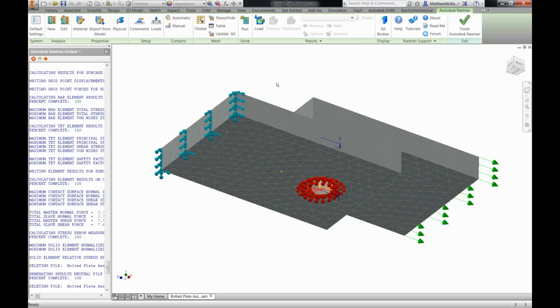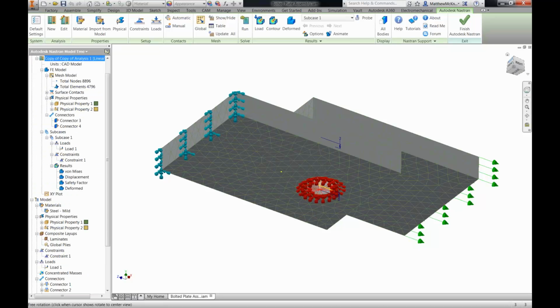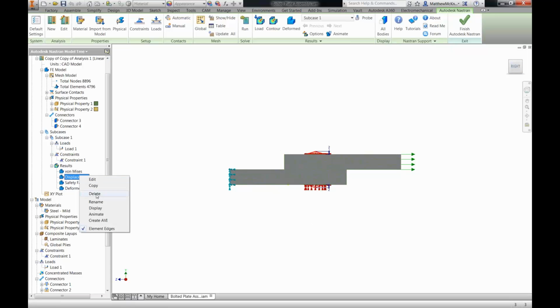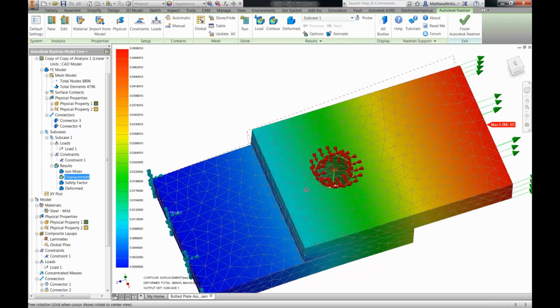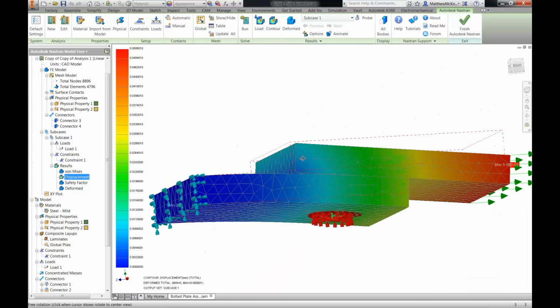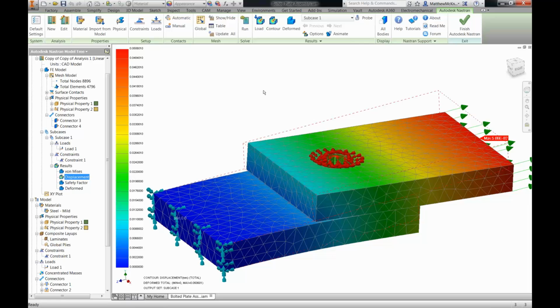And it's just finishing up now. So let's have a look and turn on our displacement plot display. And you'll see here, like we've seen before, very similar result. We're getting nice bending, very similar magnitude, and theoretically we should get very similar stress and strain results as a result of using that. So you can see here there's another way of representing a bolted connection, and potentially a way for you to represent a number of different types of connections using that method.